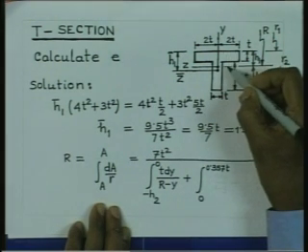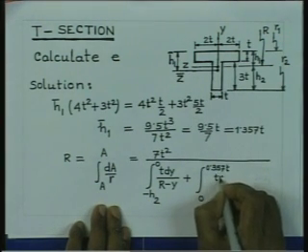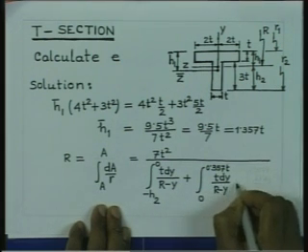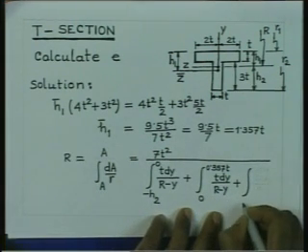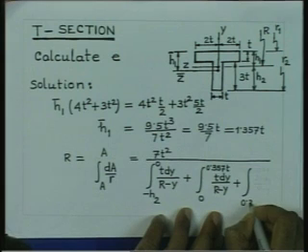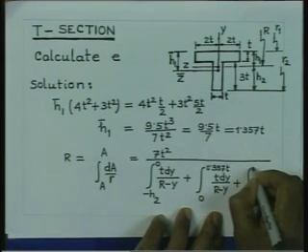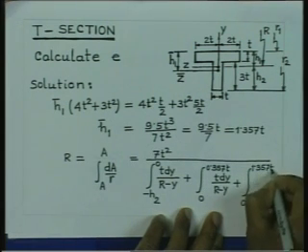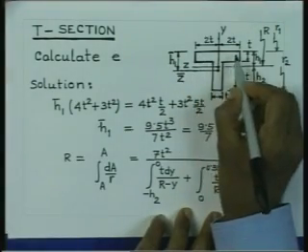Since this height is equal to 1.357 t and this is t, this portion is 0.357 t, and this dA is nothing but t dy divided by R minus y, plus the integration from the height 0.357 t to 1.357 t, and in this case, for this portion the width is equal to 4t.